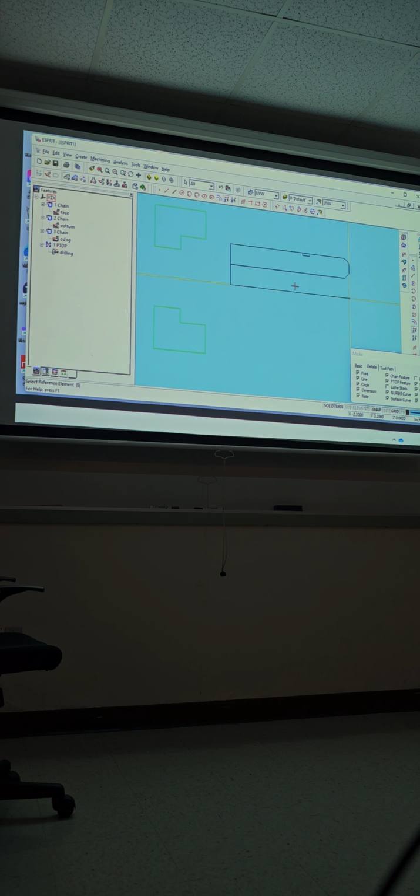All right, guys. So what do you think is next? Escape. Select the angle, chain it. Control key, and select the horizontal line. Both. Chain. Because we're going to do the chamfer and the OD at the same time. OD, ID at the same time. Just like we did. So look, it's the same as what we do in the OD, we're doing ID.